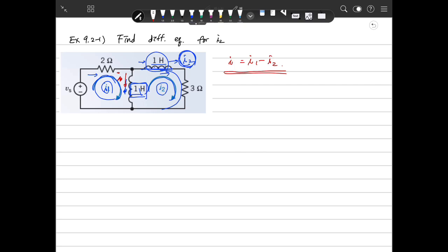Looks like here. Then we need to make an equation. And at first, what should we do? We can use the KVL here. This is Vs. Then we know this voltage VR, because the current is I1, and this voltage is VL. So Vs will be the VR plus the VL.